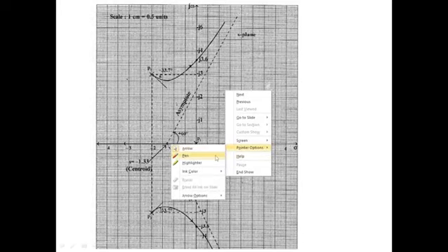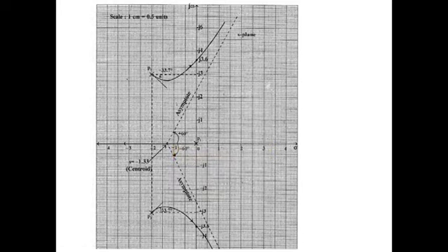Now, whatever I have shown you, I have put the same thing in the graph. You can see that this is our crossing point, minus 1.33, and this is our pole P2, this is our pole P1, and this is our pole P3. Whatever I have marked in the normal S plane, the same thing has been marked with graph sheet, right? So you can do it like this also. This is one root locus, this is another root locus, and this is one more root locus. Asymptote and root locus both are the same for this root locus problem, right? This is how.